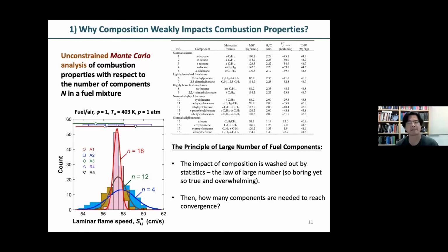If you're interested in a legacy combustion property, ignition, that's about 700 microseconds. And within this 700 microseconds, you look at this problem, you say, fuel is gone in the first 20 microseconds, 95% of fuel is gone. Because keeping in mind, this is a log scale, the time axis. Replaced by what did the fuel go to? Ethylene. You see that? Ethylene goes up very quickly, levels off.